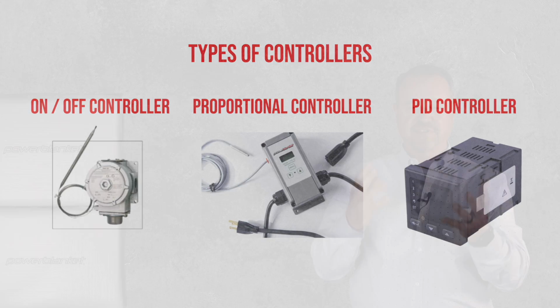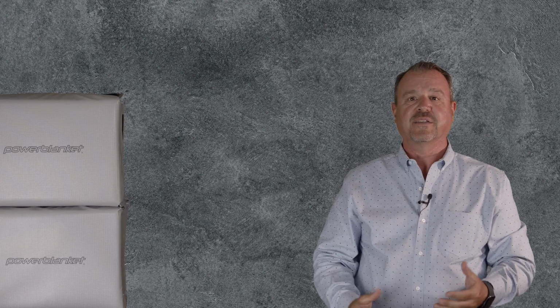The thermal loop is a system of components that all work together to keep your process at a steady temperature. The primary device in this system is the temperature controller. The temperature controller receives input from a sensor that's actually installed in your process. You have a temperature that you want to maintain, whether it's freeze protection or 1,000,000 degrees, and that sensor has to be able to accurately tell the controller what the actual process temperature is. That's called a process variable.